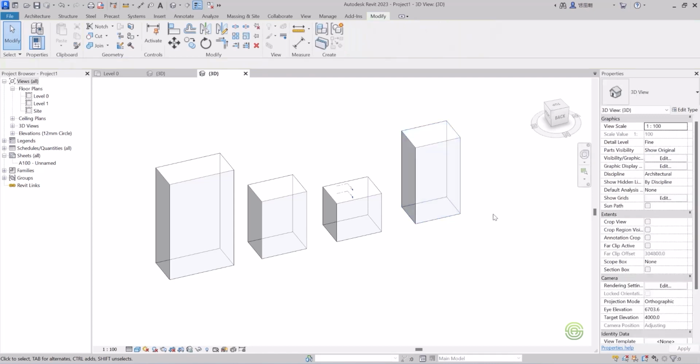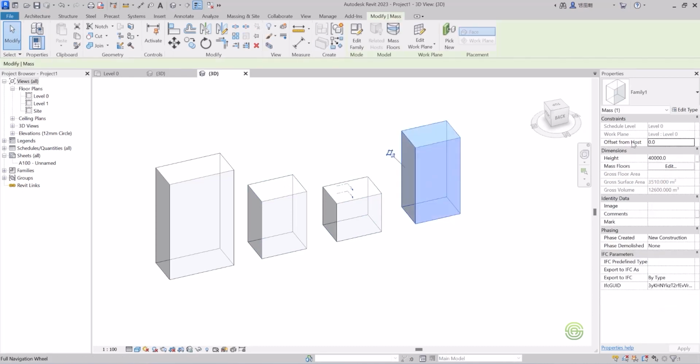Okay. So now I can easily change the height directly from the properties. When I select this object, I can change the height very easily, because I have made the height an instance parameter. So this is one advantage. But now, as all four objects have a unique height, if I want to change the length for this object and this object, here is what the advantage is.